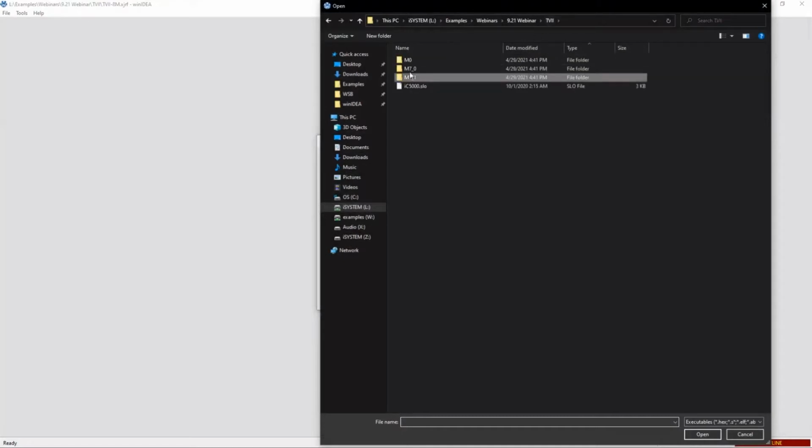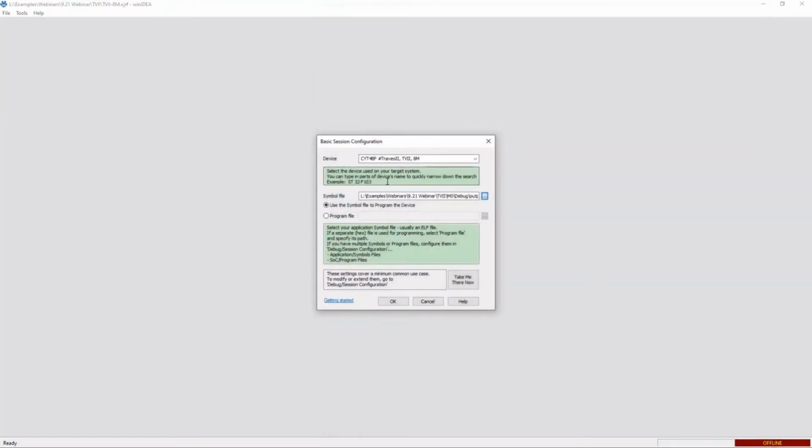So we want to select the ELF file for the boot core. So in this case, this is the M0 core. If you have a different file that you program for code different than the ELF file, so the ELF file has both symbols and code, and you can load both from just the ELF file, or if you want to load a hex file or a binary file that you actually program to the target, you can also select that file here.